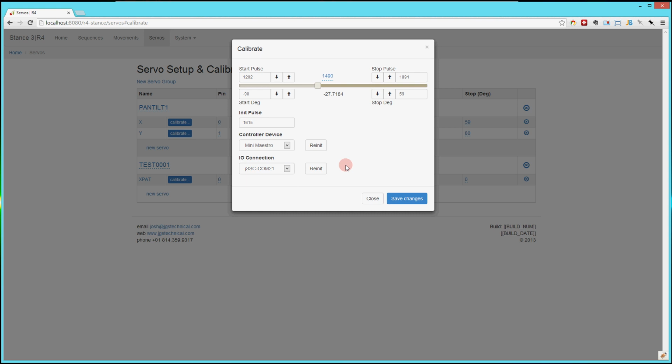More interesting probably is the network serial proxy I've been working on. So the idea there is that it's a native C++ application I've written that connects to the serial port, but it proxies over a network. There's commercial solutions out there too. But what that lets you do, I've already mentioned that you have the web interface here that can be accessed from anywhere on the internet, but underlying the server has to connect to the microcontroller via some kind of wired connection. By using the network proxy like that though, the serial connection itself can actually be over the network.